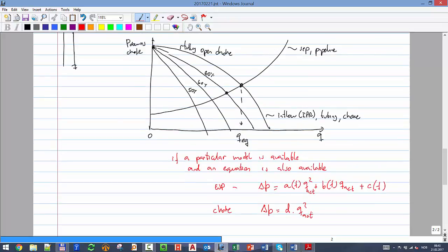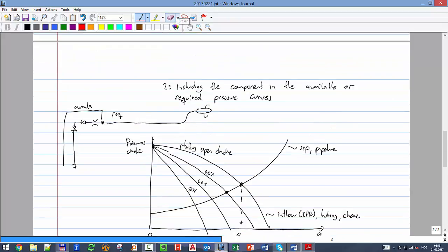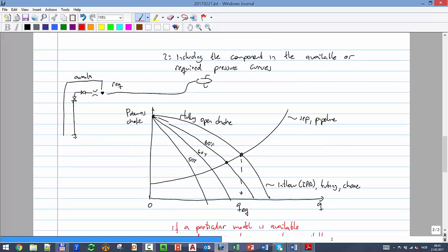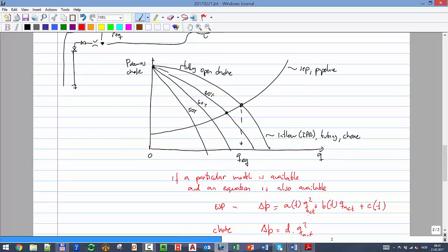So I include just that equation. For example, I fix the rate, calculate the IPR, calculate the pressure loss in the tubing, and then I come to that equation. I use the rate that I have, the frequency that I have, and then I calculate how much the pump is going to increase, and that's how I find one point in the curve or choke.